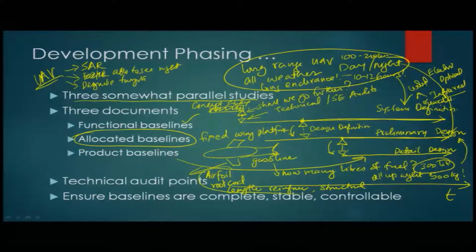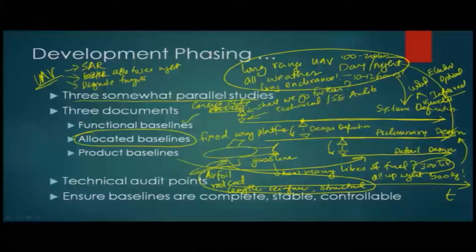So here the detailed aspects of the wing, a subcomponent, actually get specified. Someone will say about the engine, okay, it requires 12 hours, so should it be air cooled or liquid cooled, what type of engine, 2 cylinders, 4 cylinders, how many cc, what RPM, what type of propeller, what type of power generation capabilities it should have, what type of alternators will be mated to it. All those aspects come out as part of the detailed system.